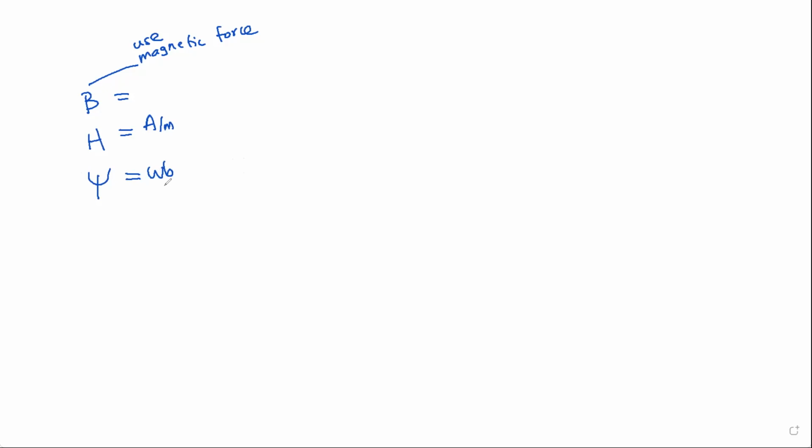So, according to my data, the unit of flux, magnetic flux, will be Webers. The unit of the magnetic field will be amperes per meter. The unit of the B field will be Tesla. We will get to that when we discuss the magnetomotive force. Right. So we will discuss the magnetomotive force a little bit as well.